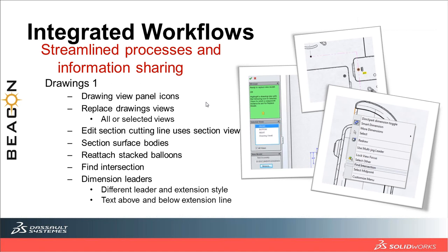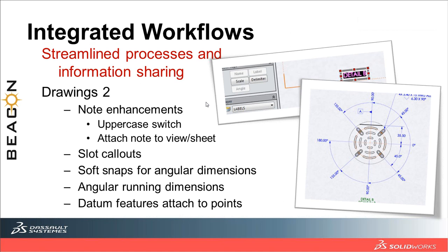So what all new changes have been added? They have completely revised the view palette that you have. Now, one more new addition, and it's actually a very important addition, is the replacing of your drawing views. One more is like you can now create section views for surface bodies as well. So this is one enhancement which has been requested by a lot of our customers. And the other enhancements is like, you could create slots and all. So we have slot callouts, and we have angular running dimensions and note enhancements. So we'll just have a look at them.